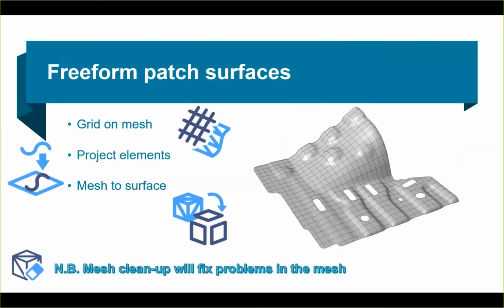So in the next version, and when I say next version, I mean the next software update, we're going to include the mesh cleanup. So the mesh fixing of, say, intersecting triangles and overlapping, just problem areas in the mesh. We're going to try and build that into the command, so you shouldn't have to do it. But it's really useful to know about anyway, just to verify that mesh. But at the moment, it's a manual step, so you'll see me doing it in Designer.